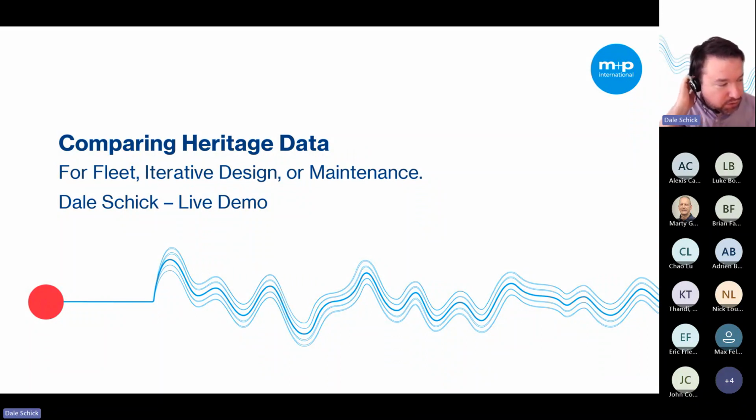Every time you run an acoustic system and you do an initial shaping run, or you do a verification every year by running a test just on its own or with a dummy mass, you should be comparing the voltage draw, current, and the impedance of the speakers, which I know the ARS drive does a good job of monitoring, and then look at the drive output from your control system to make sure that 1 volt equals 100 dB, or whatever that scale might be.